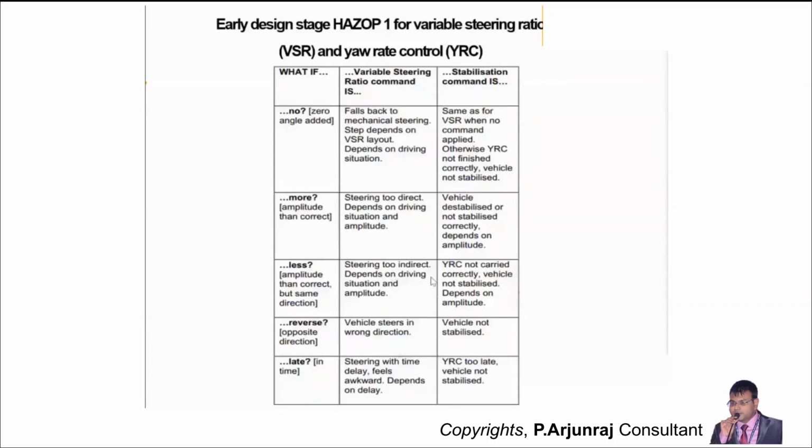One for you to consider is ISO 26262. And here you are not only considering ISO 26262, you are also going for the external requirement called GOC, and even ISO 21448 for SOTIF, what we have seen, that also needs to be considered. But with electrical electronics, you go with an HARA in a manner where you have severity, probability called E, and controllability called C.